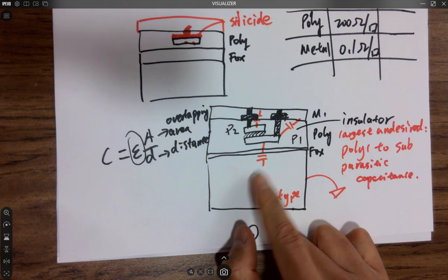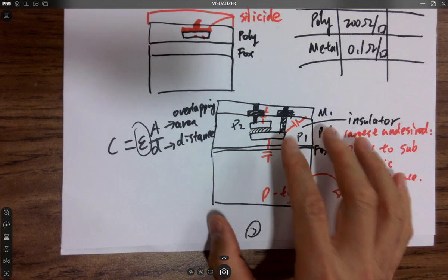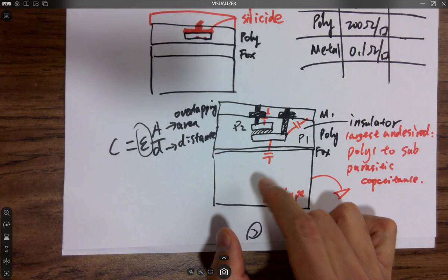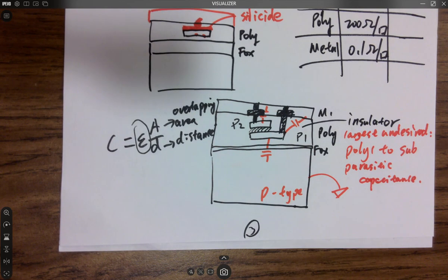All these parasitics will contribute to the timing delay and give errors. So you are not fixing individual ones. After the design, you run timing and see if certain nodes reach the required timing. If not, you come back and optimize it. There's no way I can fix individual ones. And usually for digital VLSI design, 50% of the design period is on timing.